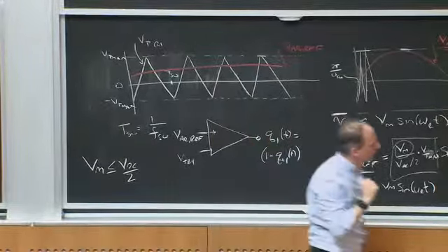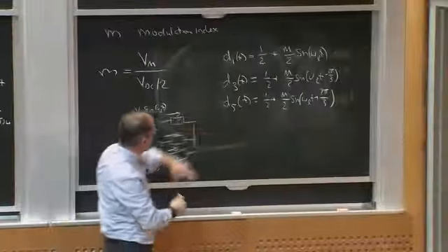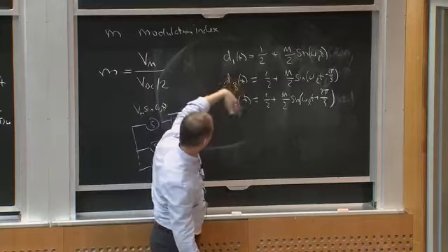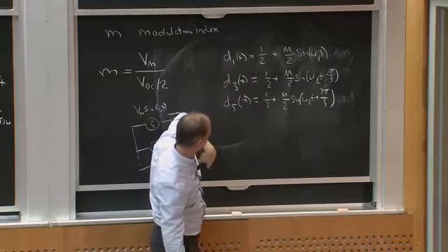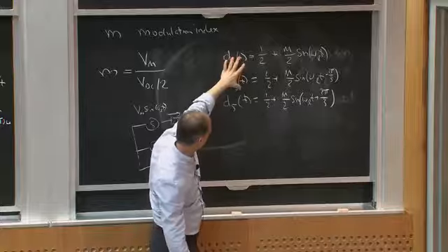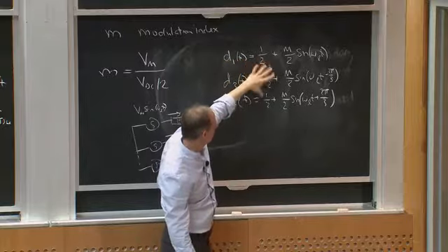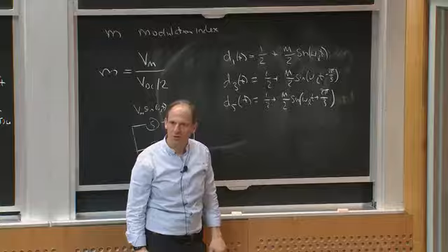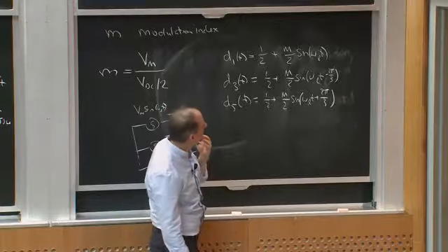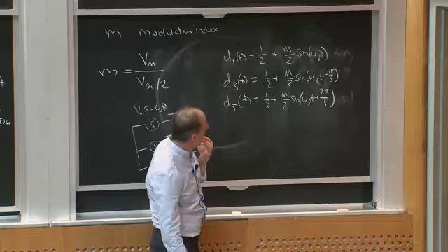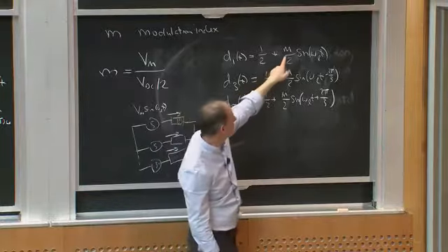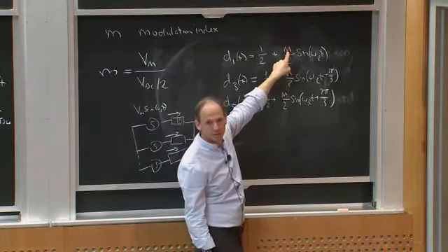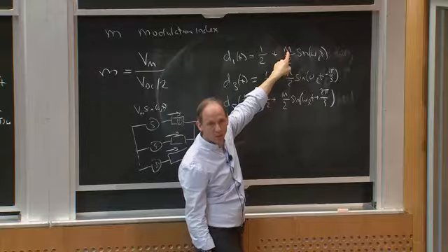Okay? And what we said was, basically the average voltage at that node with respect to ground is proportional to the duty ratio. With respect to the midpoint, there's this 1/2 of the bus voltage in there. Okay? The question would be, I have a trouble that I'm limited to making m less than 1.